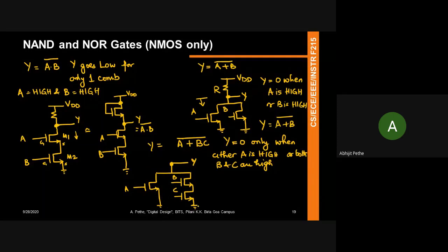So if I think of the circuit, I can implement this again. Remember, this is easy to implement because the whole thing is under the inverter, right? So any NMOS logic or CMOS logic likes to have expressions written in this form as the complement form because it's easy to implement. So therefore, NAND and NOR become our universal gates because they're easy to implement in CMOS, right?